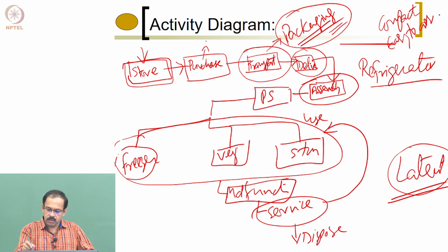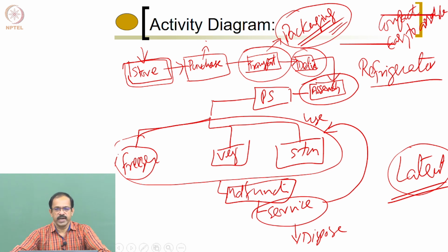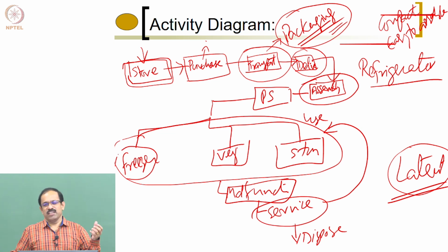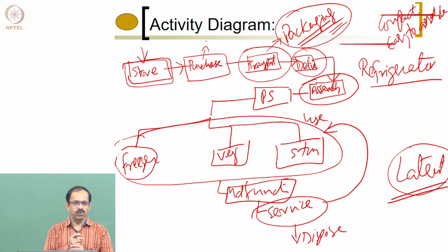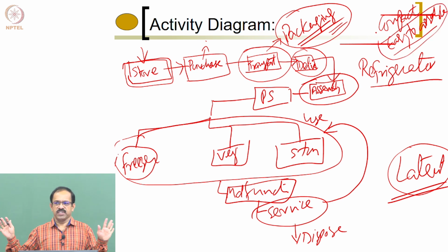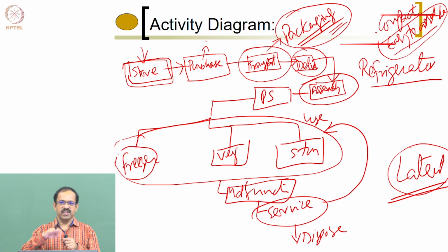one latent need you can identify. When you say easy to assemble, what do you actually mean? Yeah, fewer parts, easy snap fit, or no need for a large number of tools. So these are the things that make it easy to assemble. But we normally look at it from the design point of view, easy to assemble is a requirement. How do you make it easy is the next question that we will answer later. Okay. So easy to assemble is the requirement.